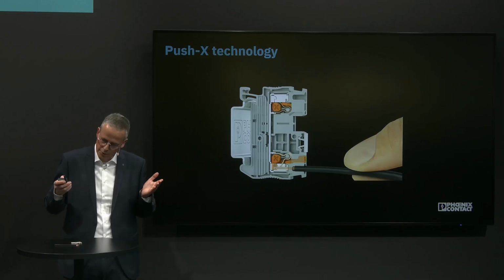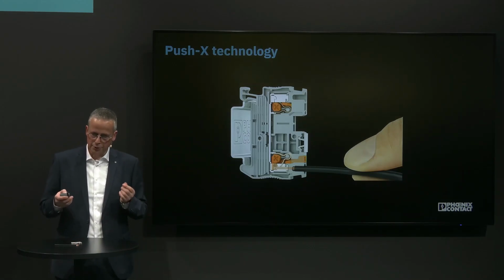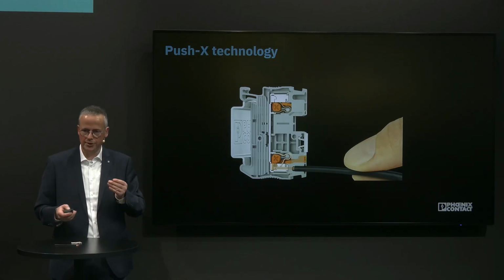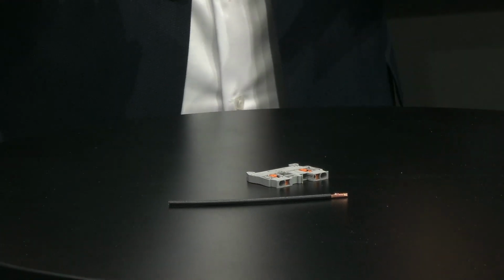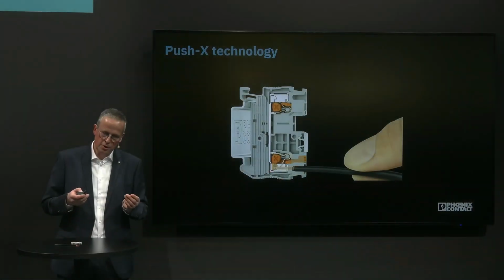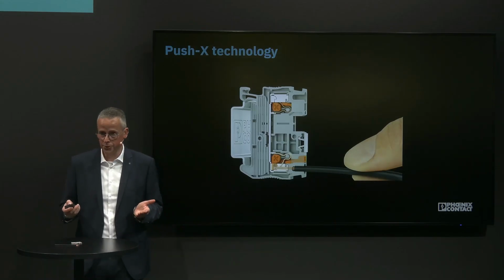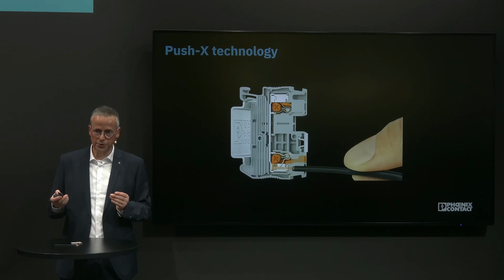If you have a crimp and a ferrule, you have a defined process. The crimps are standardized, the crimp tools are standardized, and the whole process works according to a standard. And you really have a pretty good connection due to a standardized contact. And this is the reason why customers are using ferrules.